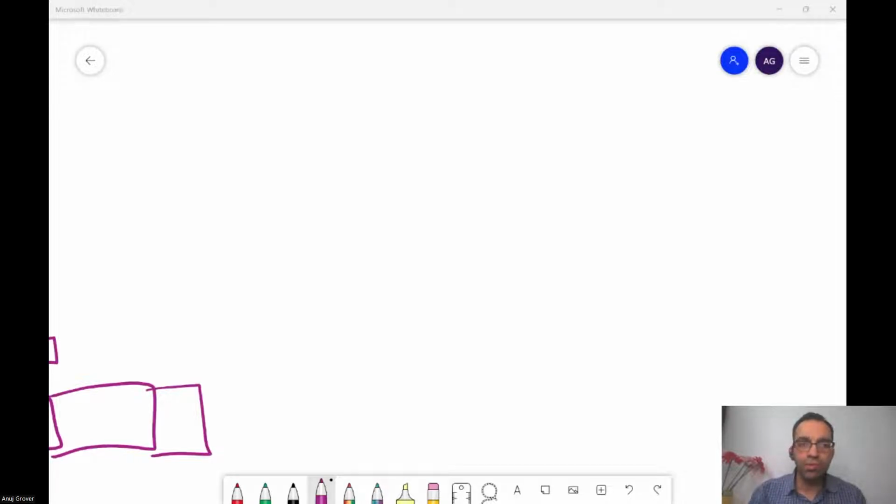So in the IO design project, pre-charge, write driver, and multiplexer. The separate one for write driver is about negative bit line write driver. The one that we're talking about over here is a regular write driver. It does not generate negative bit line. But the separate write driver project that is listed there is about the negative bit line. So the negative bit line will also be generated there. It requires additional design of a charge pump and so on.